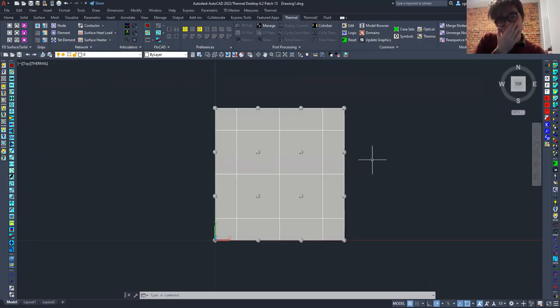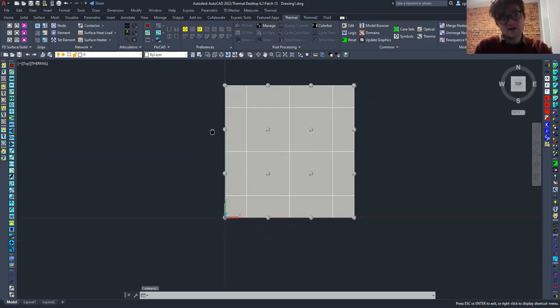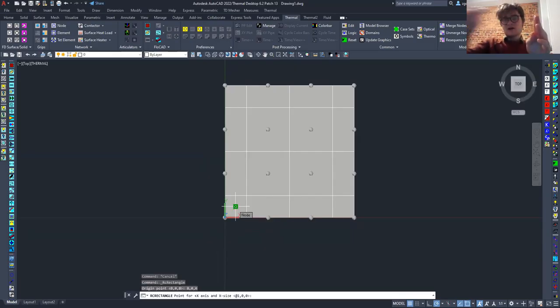So the next thing I would do is make the ones that'll be coming out of the screen, same direction. So go ahead and hit the square again, or the rectangle there at the top. And again, don't rely on the GUI, rely on your own. So do 0, 0, 0 again as the origin. Like don't click anything, just type everything is what I would do. And then for this one, let's make the one that goes along the X and then pops out. So for this one, you want your X point to be the same. So 0.1, 0.